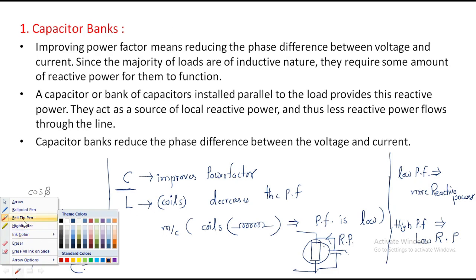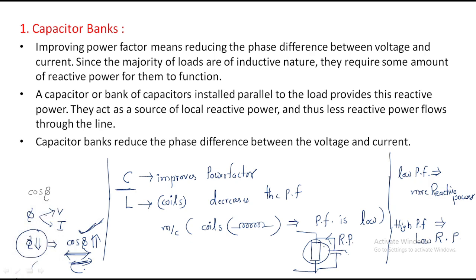And by using these capacitor banks, we will decrease the phase angle between the voltage and current. Then automatically the power factor will be improved.